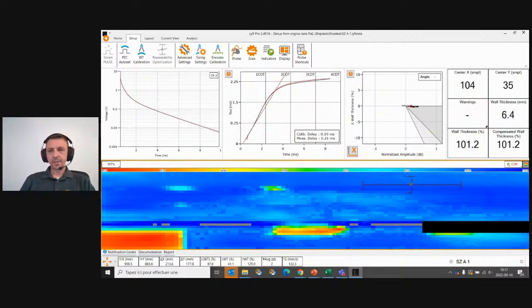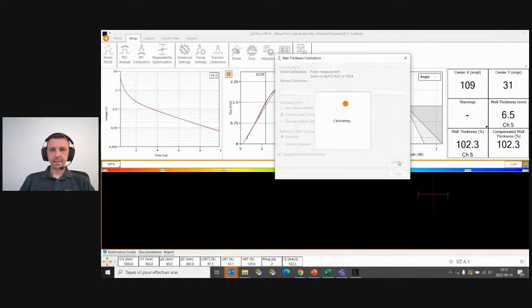Now, before starting the analysis, it is always good practice to recalibrate over a near nominal area. So we'll look for a good candidate for that. On the right side, this is a good place. I want to stay away from any special feature overlaps, and in this case we don't have overlaps because we don't have a jacket, any mass effect, edge effect, etc. So this one is a good place. Just click calibration. I will recalibrate there.